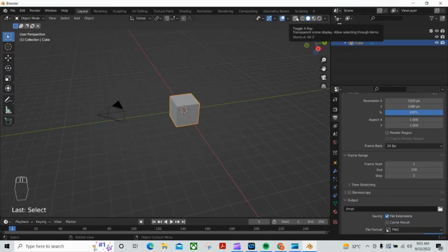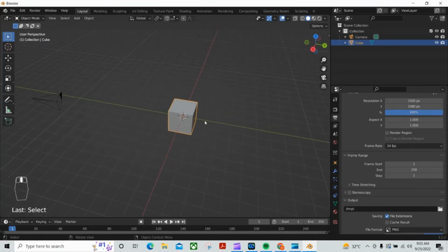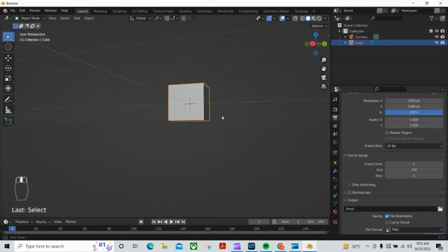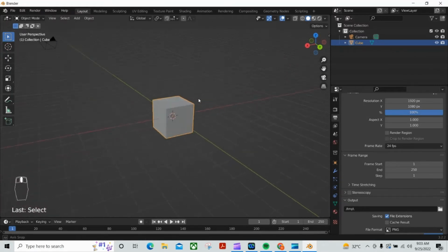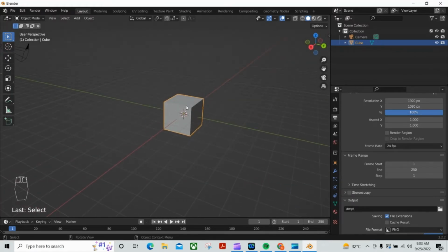So here there are some four views. To see your object in different views, you can click on this. You can select your object, and you might have seen the viewport setting view. So this is the wireframe. Wireframe is something you need when you want to select a particular vertex or something.